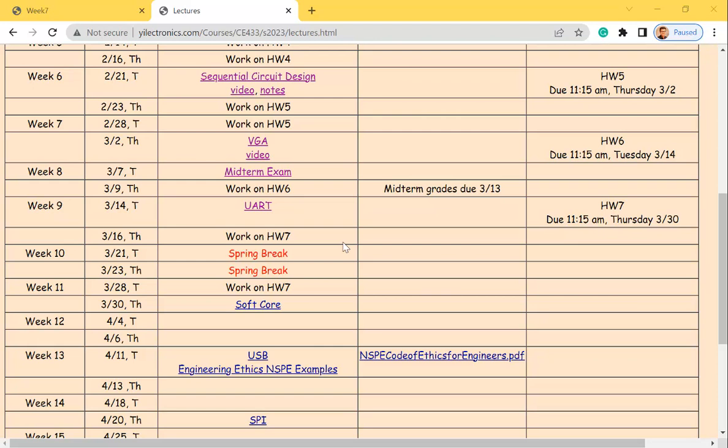Or you can use a soft UART, which is just a library you can use, but you don't want to read the drivers for that. The soft UART is written in C++, and you find another RX and TX pins, and then you use the existing RX and TX from the Uno board through the USB, and so you can send the data to the monitor of the computer.